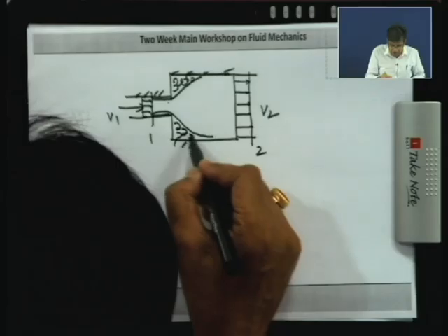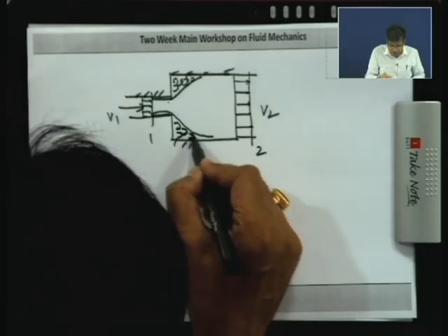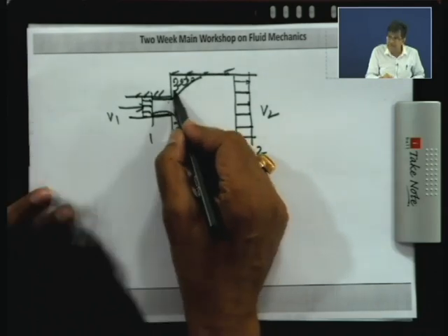If the wall is at rest, that is the no slip condition. The kinetic energy of the fluid particles, the velocity of the fluid, becomes very small near the wall. They cannot surmount the adverse pressure, so they flow in the opposite direction. This is the boundary layer separation. Because of this separation, there is flow reversal, eddies are formed, and the pressure is sufficiently reduced.